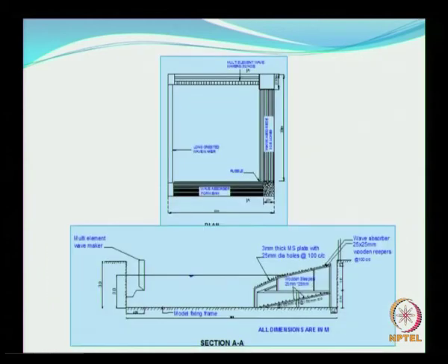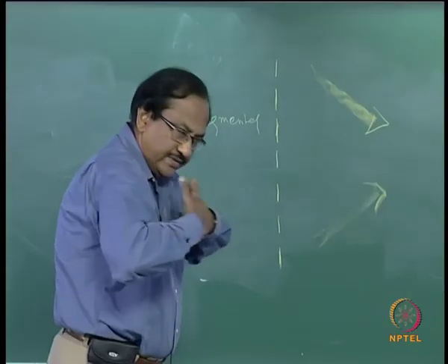So this is a view of the wave basin in the Department of Ocean Engineering, wherein you see one wave maker, the long crested wave maker, here on the left. The size is 30 meters by 30 meters, and the water depth is 3 meters. The LCWM, the long crested wave maker, can move as a single unit and does not have any direction.